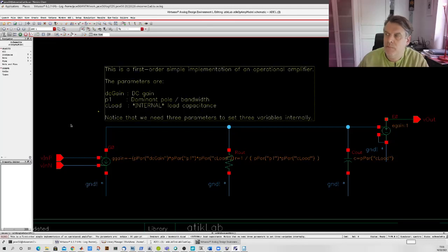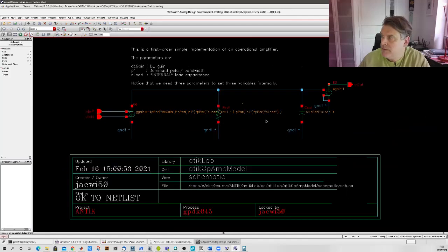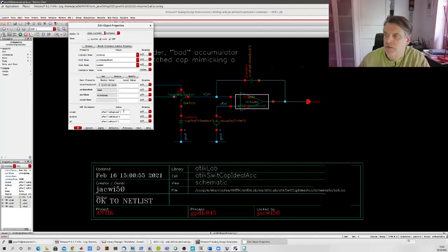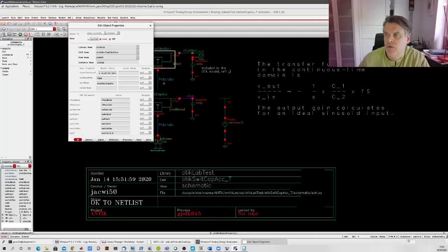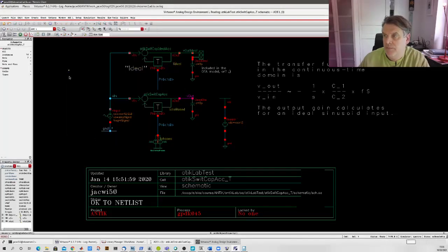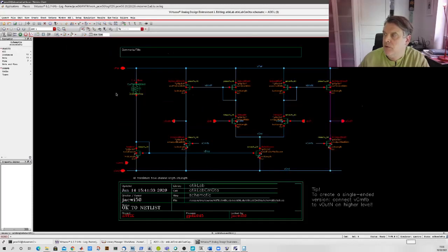And then you can sweep them. But maybe you want to sweep some other parameters to understand your circuitry. At least take a look at what's happening inside here so you understand what's going on. Those are the parameters, capacitive load, DC gain, and pole frequency, that you pass on to the circuits. So a lot of parameters are also picked up by the simulator. And then you have the same, but with your op amp. In this case, the default op amp settings are included.